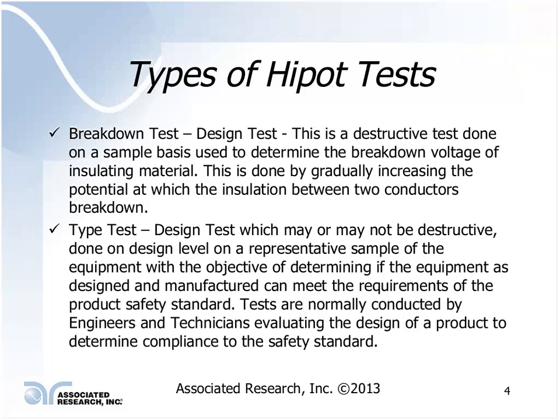The number of tests, normally you might run 5 samples on it to come up with an average of what the actual breakdown voltage is of that material.